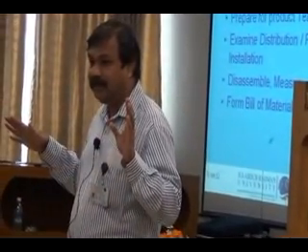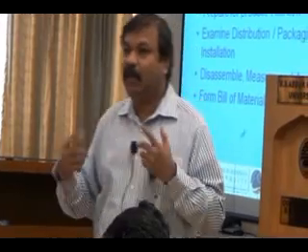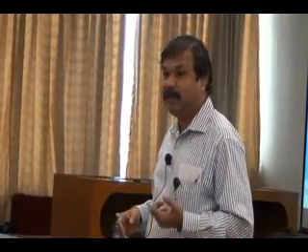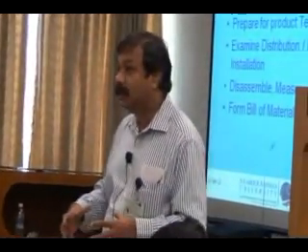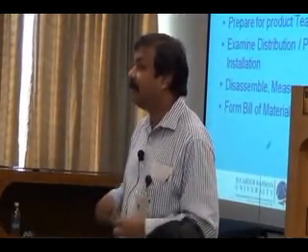Am I making sense? Are you able to understand? See, if you want to do reverse engineering, what will you do? Take individual components and measure, prepare a CAD drawing using AutoCAD or better software, so that I can finally arrive at the complete design. If I want to benchmark, then you dissect your product as well as your competitors' and then see how the various subsystems perform.